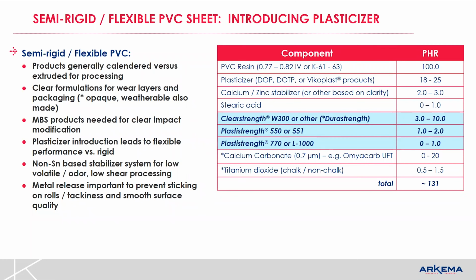Okay, next. Can you talk a little more about the difference in volume-based versus mass-based loading of a Brabender? Do you see issues with torque readings when doing volume-based if there are shifts in bulk density? Yeah, so this is kind of a problem of your own creation if you do it, right? So I think the important thing for me is that you measure the bulk density of your compound and know what it is.